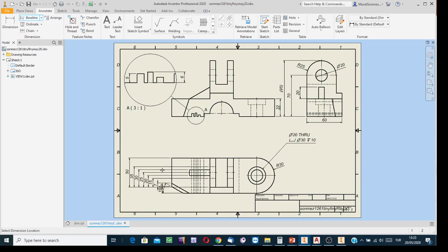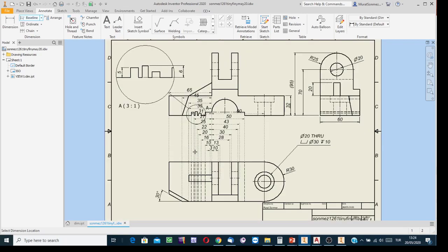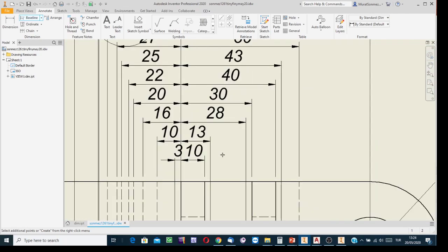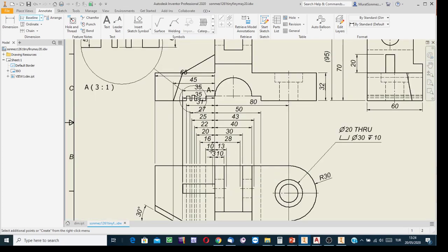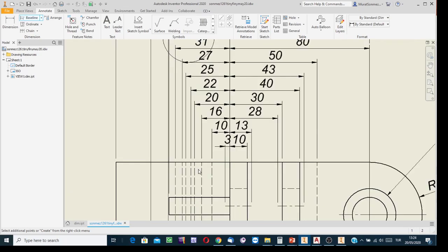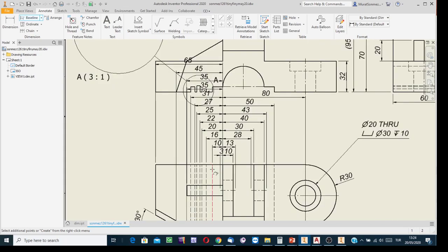You see? Now I selected all of them and then move the cursor in this direction, and if Inventor finds an entity, then for all the detected entities, it shows the dimension with one click. But you see, although it is a facility, for instance, this dimension, there is no need to show it. You know the rule, if on the projection the entity is hidden, then we don't show the dimensions. But Inventor, in using this tool, couldn't distinguish that these are hidden, so it shows their dimensions.